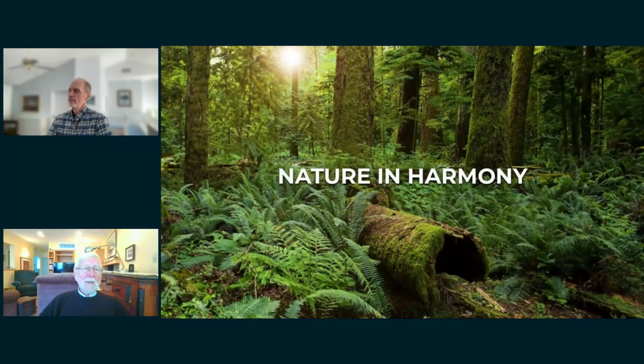Of course, the most direct is, as the inspector, you're looking at the problem. You know how widespread it is. And the tape sample could be on a 1-inch spot, a 1-inch colony, or on the entire wall, like some of those terrible situations we've seen. The sample is going to be the same. What the tape sample will tell you is it will pick up the actual mycelium. It will distinguish spores that are just sitting there from colonies that are actually growing. So I like tape samples.